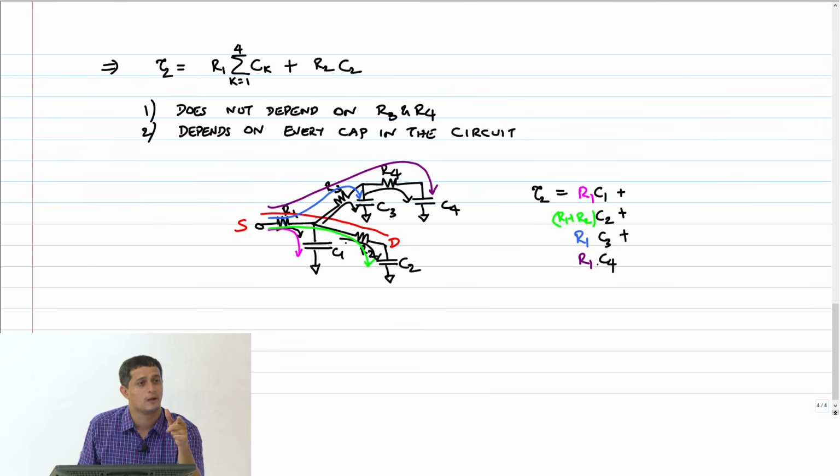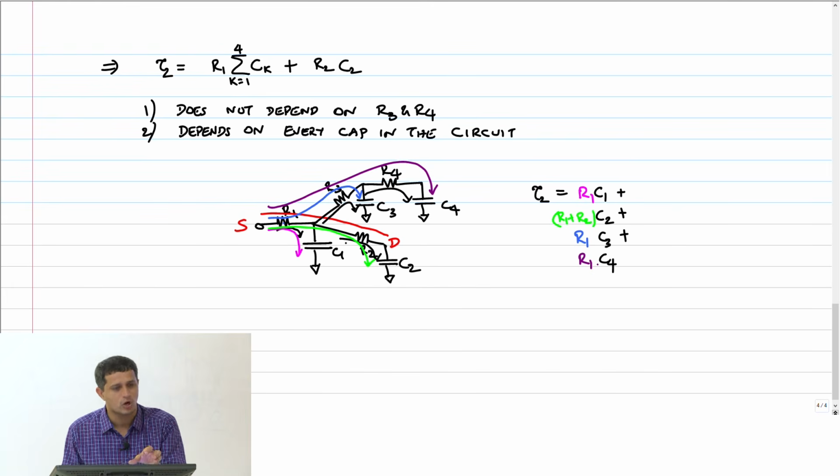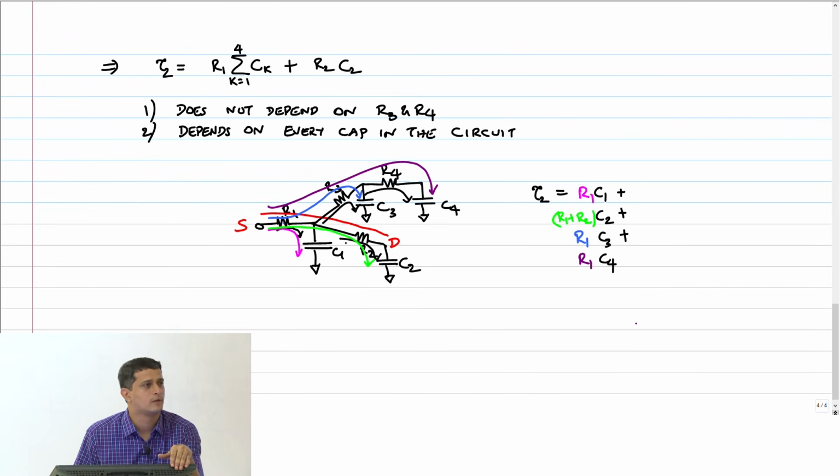What you should check is maybe this first order approximation doesn't work at some very high limits. That you should check through simulation, and that may break. From the first order approximation we are getting this. That is for maybe a reasonable range of resistors and capacitors where this works. That you have to go and double check in simulation where it fails. Okay. So any questions here?